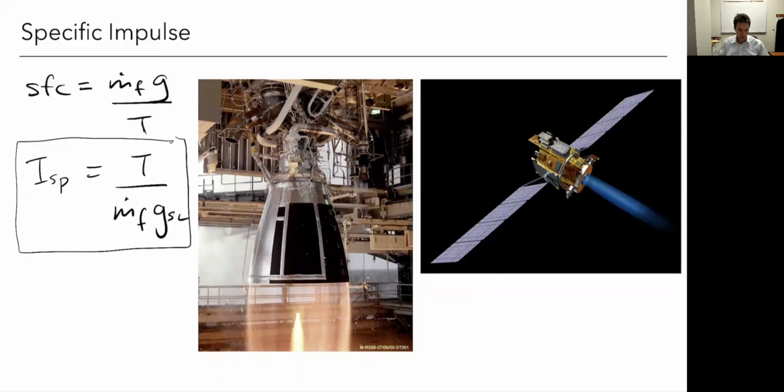Let's jump right back in. We've been talking about some trade-offs in thrust and efficiency. Remember, for the launch vehicles, you get a lot of thrust, but with a low specific impulse, right? Low efficiency. Whereas for, say, an ion engine, we could get small amounts of thrust, but relatively speaking, high efficiency, a high specific impulse.